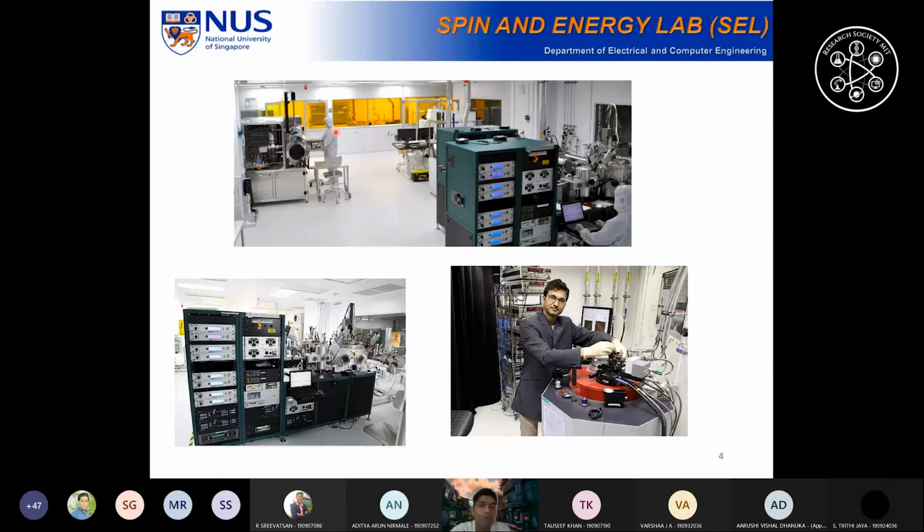So a very nano pattern, because with nano devices, if your device is a nanometer, you cannot see it in an ordinary microscope, right? So you need to use electrons. So you have this electron beam machine. You use that to see the device, and it can also be used for patterning. Okay, so you put a photolithography and then you pattern using this electron beam.